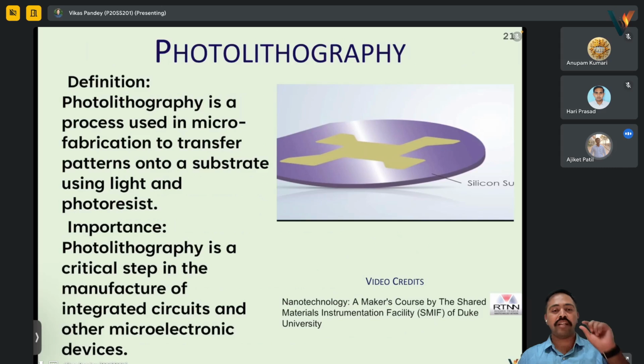Here both of these layers are patterning the same material, not two different materials. That is how we are improving the pattern resolution. With the same material, instead of doing lithography once, we are going for lithography twice, because the patterns were too dense to be resolved.